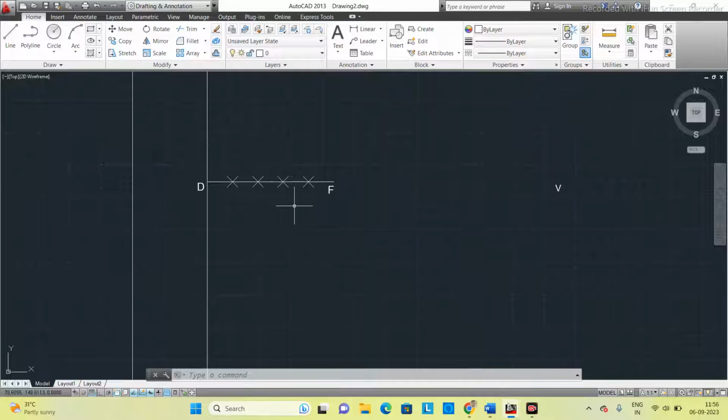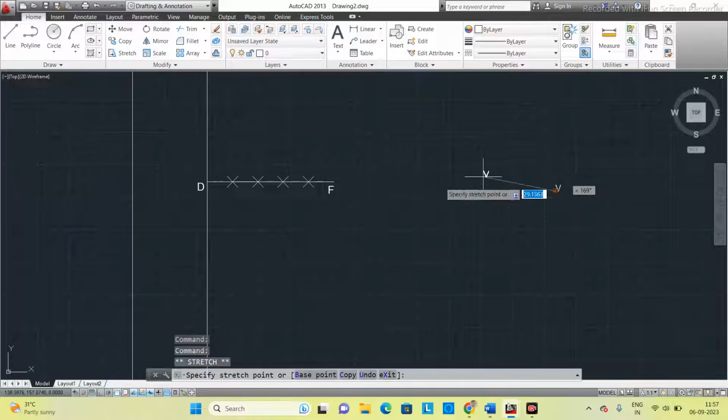So next, I'm going to place the vertex. You have to place the vertex again based on the E value. So the E value is 2 by 3. That means in the numerator 2 is there. So you have to fix the vertex at the second point from the focus. Okay. So I'm going to fix it here. This is going to be my vertex.